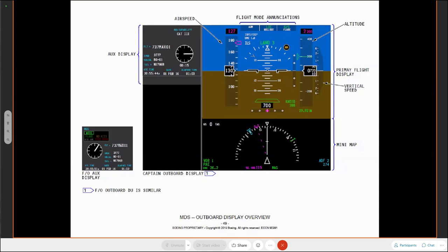It's an extremely reliable and an extremely accurate means of landing an aircraft. It doesn't require any real guidance information received from the ground, like you do with an ILS, localizer and glide slope information that you are actually receiving. All you're really connecting to is a ground-based augmentation system that provides you with error information to do with the current satellites that you are tracking for GPS. So it takes the error out of the satellites, what we call a VHF data link.